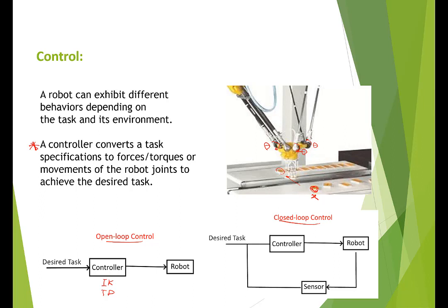The position that we know is not exactly accurate. So when the robot goes to pick it, it doesn't exactly get there. It gets to a point that has a difference, let's call it delta x. This is an error, and it cannot pick the object. Therefore, open loop controllers usually have errors and don't work very well.